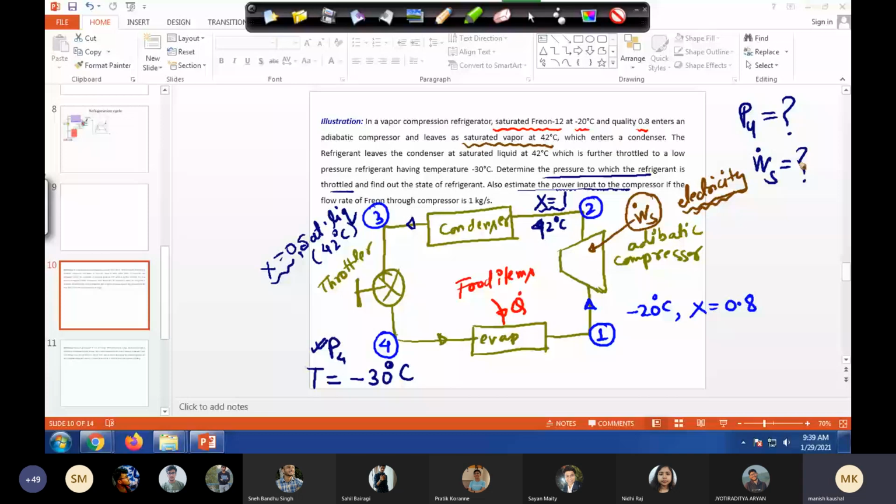Okay, so first of all, what we should remember, let's start from this compressor unit. We know that for the compressor, if you see the first law, that energy equation, there is no heat transfer. The only thing we are transferring is the work transfer. And then we ignore the delta K and delta P, the macroscopic potential energy and macroscopic kinetic energy. If you ignore these, then when we wrote the equation of the compressor, we discussed it in detail.